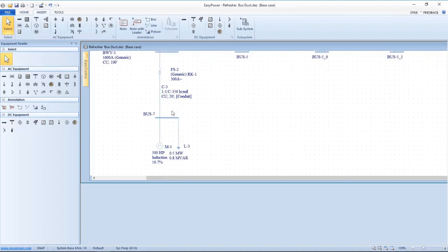and because if we're considering this as a lumped load, what do we put in as the protective device? Well, certainly if we're adding up all the current, then potentially there's some argument to be made that we should add up the total current that could flow through the protective devices. But what that gives us is an artificial number when it comes to calculating incident energy.